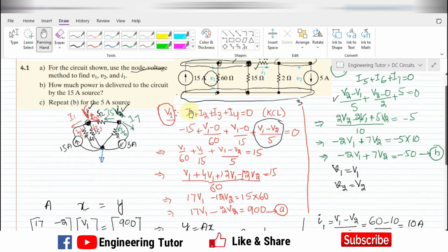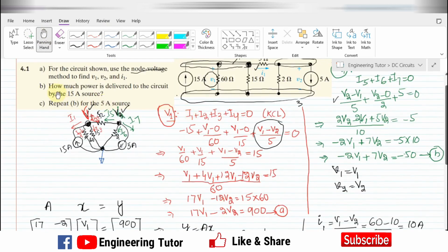In order to find the solution of part B and part C, we need to know how much power is delivered to the circuit by the 15 ampere source. So this is the 15 ampere source, the current is already given. In order to find the power it delivers, we have to find the voltage across it, which we have also found out, which was V1. So the power supplied by this one is equal to P equals IV. Similarly, the power supplied by the 5 ampere source is also P equals IV. So now let me do it.